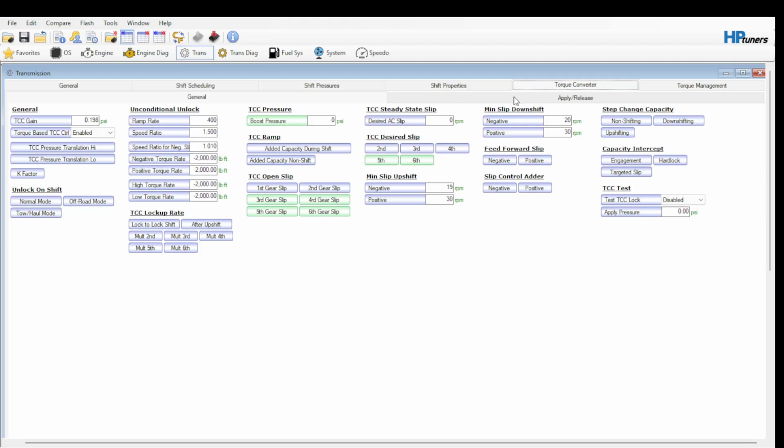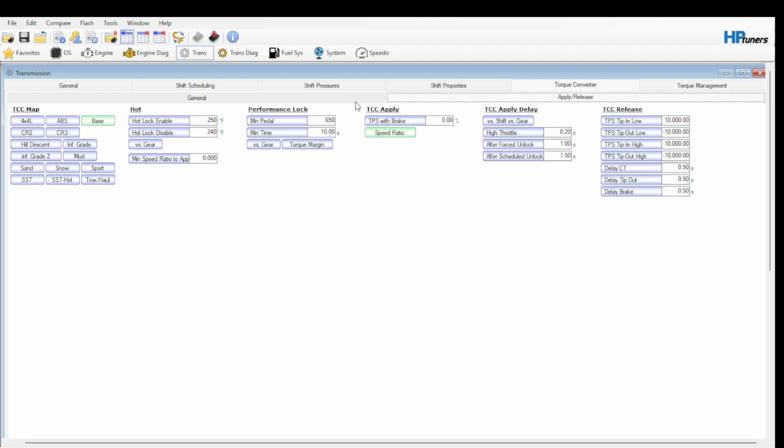And if you're trying to do a shift in that state, well, telling the transmission that it needs to convert an expected positive value that is now a negative value into a pressure, well, the pump's not going to turn backwards. The pump's not connected to an electrical pump that can pump backwards, right? It can only go forwards. And so that's going to be a potential issue.